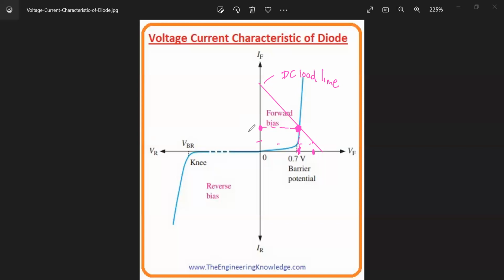So it considers the diode as a kind of resistor and gives a DC load line. But always remember, the diode can only actually work in the voltages allowed by the characteristic graph, because we already know it can't go higher than this. So we plot these two graphs in one graph, and we can figure it out at the intersection point of these two graphs.